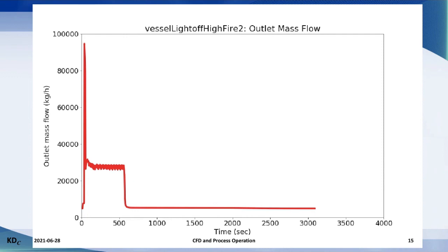It would introduce a very high pressure drop, could cause equipment damage, it could deform the hold-up plate or the hold-up trays. If it's downflow, it could fluidize the bed. If it's upflow, we may get poor dehydration performance. We could have all sorts of things that happen.